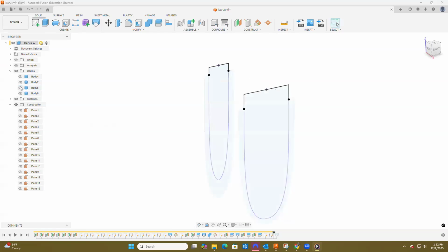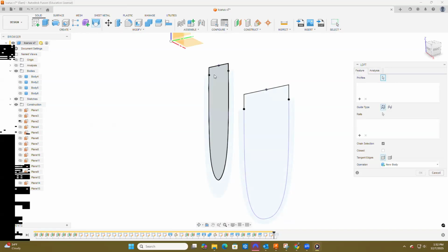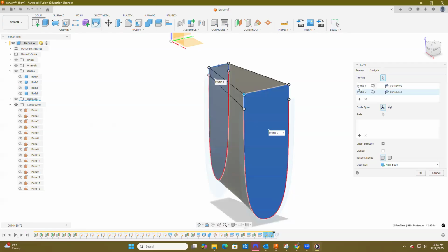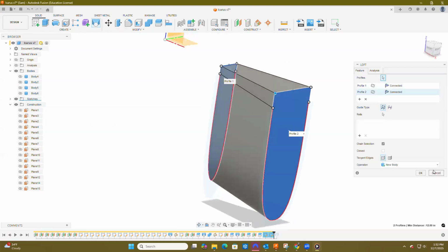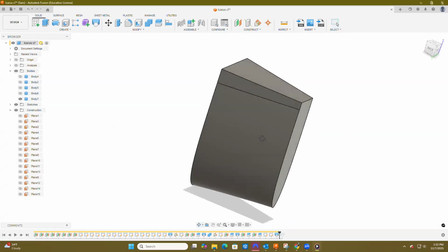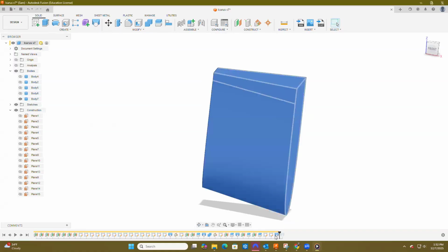Now we are going to want to loft these cross sections. So by doing that, it's going to show us what our foam mold will actually look like when we cut it out with a hot wire. So we lofted it, and that's what our cross section is going to end up looking like, hopefully, when we hot wire it. So we have our reference to the ground and our cross section, so all the heights.